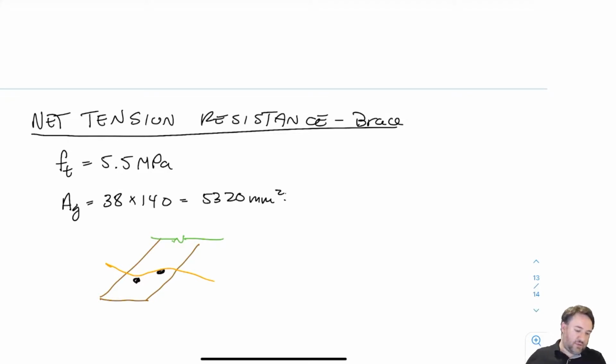It's found in 12.2, where we talk about net section, 12.2.2.5.2. For a bolted or lag screw connection under parallel to grain loading, staggered adjacent bolts or lag bolts shall be considered to be placed at the critical section, so they'll be at the same section, unless their spacing center to center parallel to grain is more than 8 bolt, screw or lag screw shank diameters.